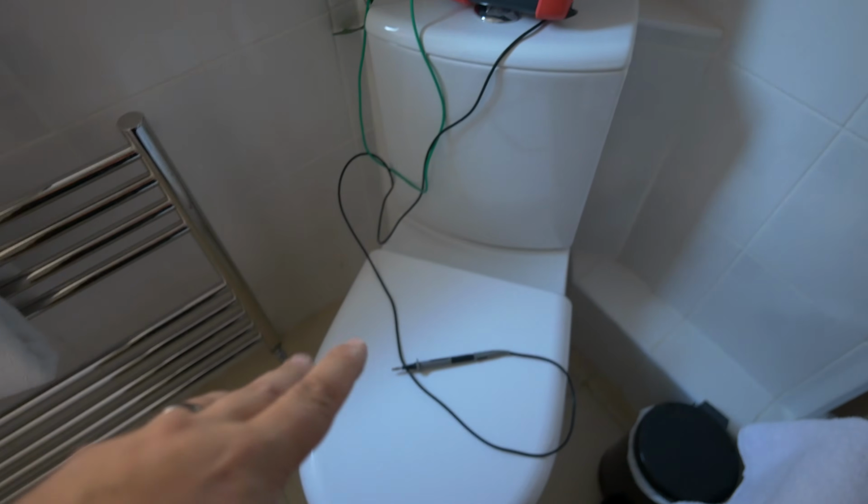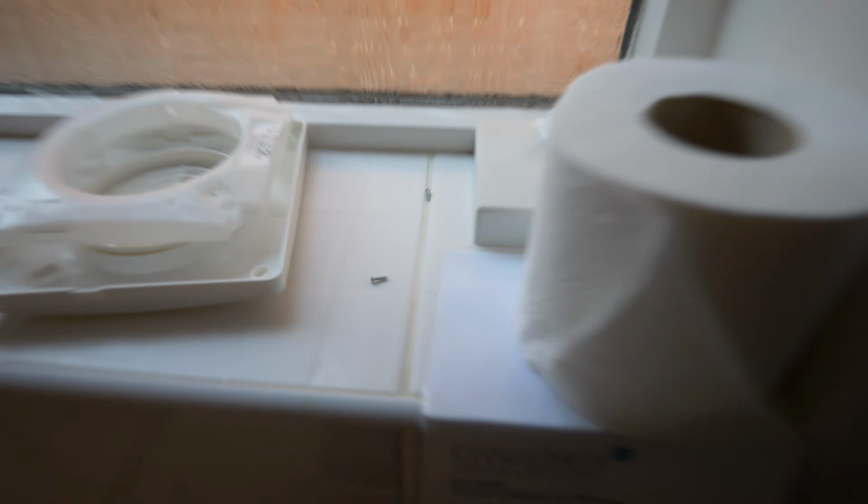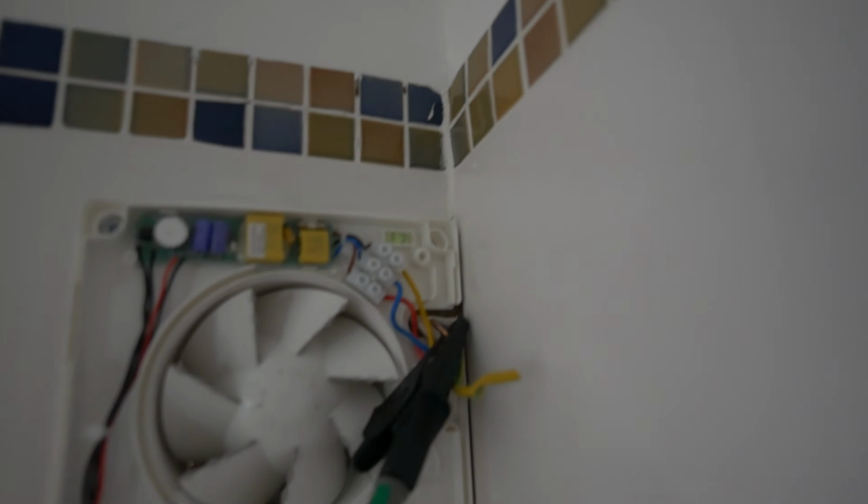Little tip, when you're opening things with stuff underneath, close the toilet lid, plugs in the sinks, make sure you're not losing any of the little screws like these ones down there, because you'll regret it and you don't want to be fishing them out from a drain or a toilet. Now the CPC has been brought into this fan, but it's not terminated because it, again, class 2 item, so there's no need to earth it, but it's in there, so there should be earth continuity to it.